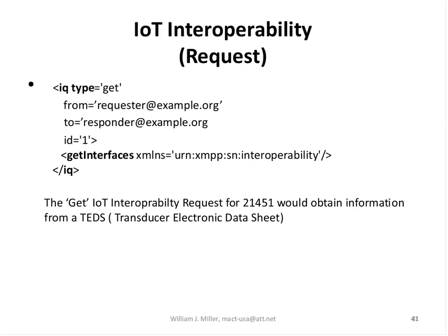And again, interoperability takes two forms, which I'm going to talk about here. Because we're riding on the 21451 standard, as I said earlier, and I mentioned the TEDS, the Transducer Electronic Data Sheet, we had to address something that I'm going to show you. Because those legacy systems used XML, there's been changes, obviously, over the last 15 years. But again, we have to try and find a way to deal with that. And I'm going to tell you how we did it. In this particular message, we're just asking what kind of interfaces you have. Move forward to the next slide.